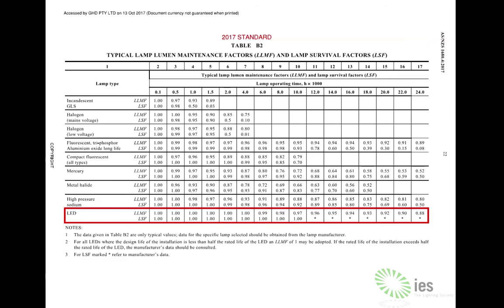If you run it for 10 or a million hours, that's when you run it at a really low current. But the moment you actually start to use the chip, that degrades, and the other bit is they do have curves. But again, once you include for cooling and how they actually intend to run it, that changes as well. So there's plenty to consider there when it comes to how you get your data and if the data is correct. Always validate your data with a sanity check and what you're expecting to see.